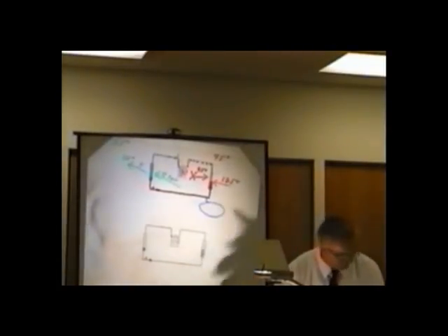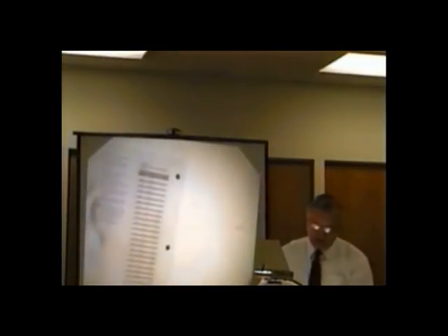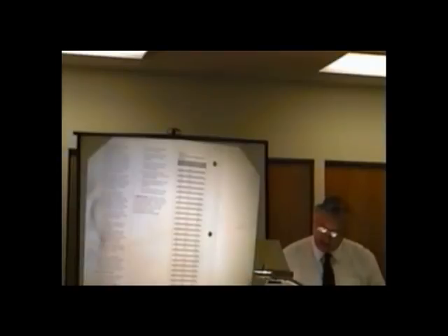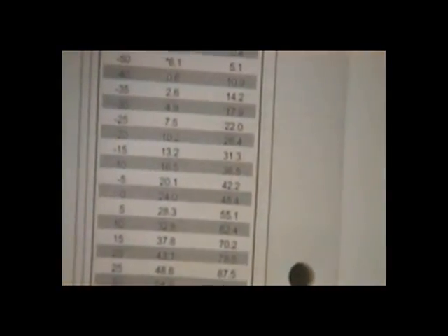Now, this is R22 that we're talking about here. So R22, now you don't have to keep flipping your pages back and forth, but in your handout, on one of the pages, we actually have a PT chart. And if we look at 125 degrees, this is R22, temperature on the left side, and the pressure on the right side. By the way, we also have the pressures for R410A, and we'll talk about that later. But if we have 125 degrees, that means my pressure would be 278.